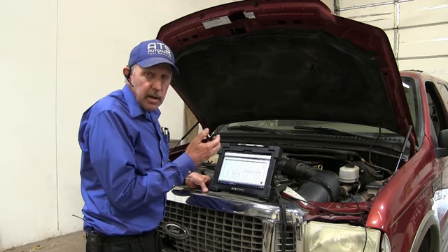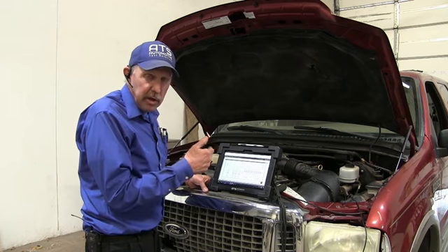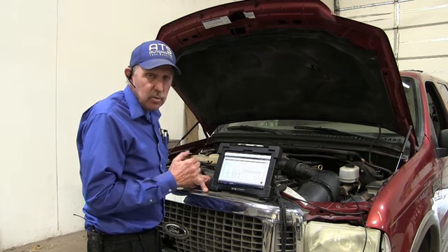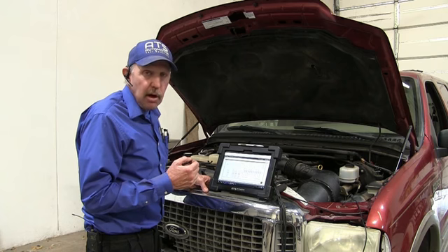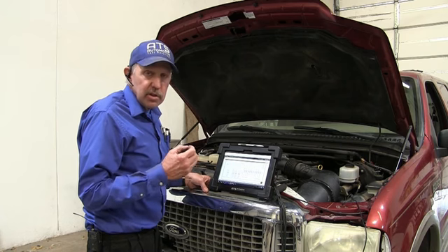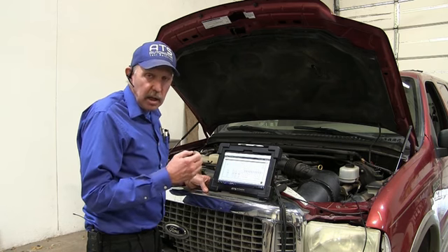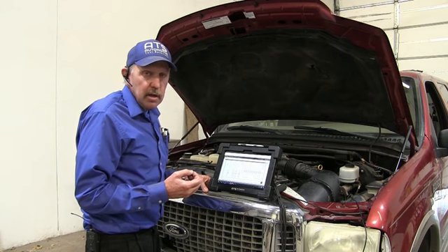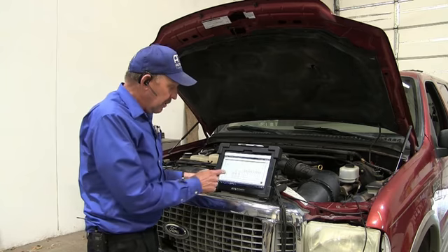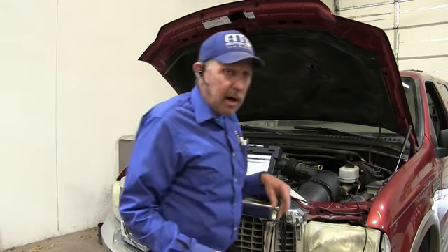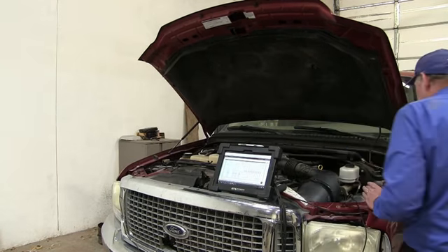Now to make sure that that's the signal I'm looking for, I'm going to jack the rear of the car up and I'm going to run it with the wheels turning so we can check this signal, because what I need to know is what's happening to this signal. I've seen these sensors go out and the sensor starts to break down and it'll cause these cars to stall. It's something I've seen in the past, so we're going to start there. So I'm in this wire right here. Let me show you that wire.